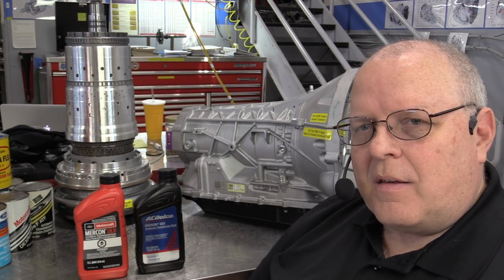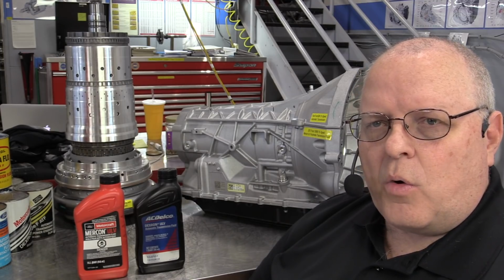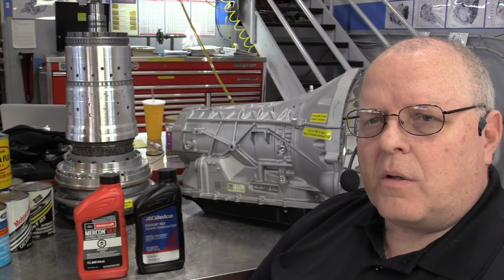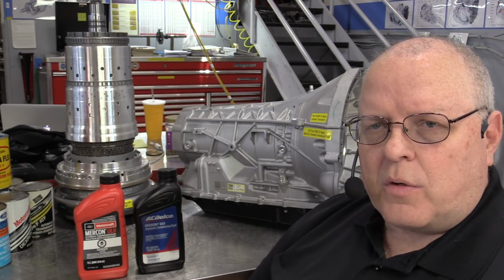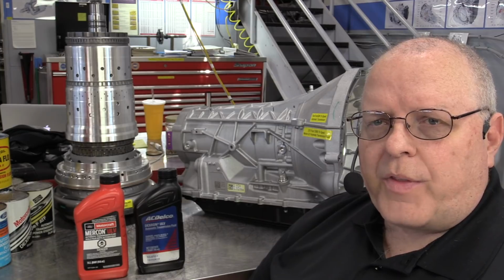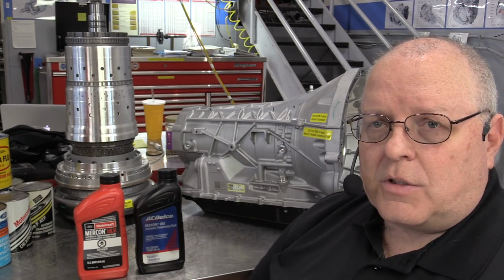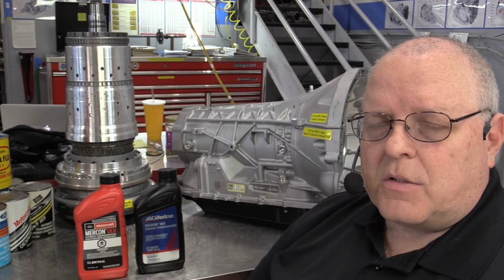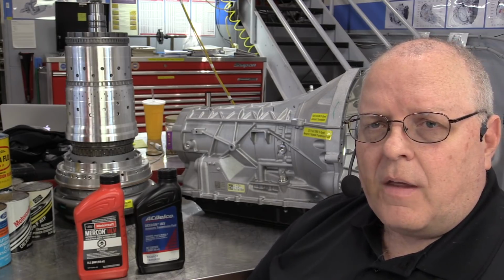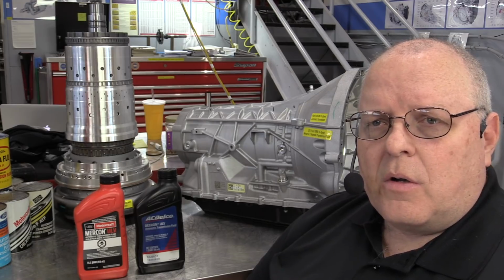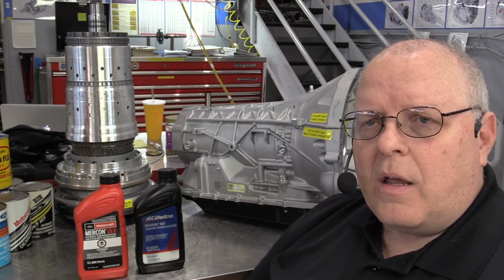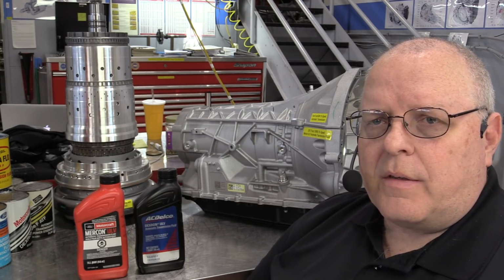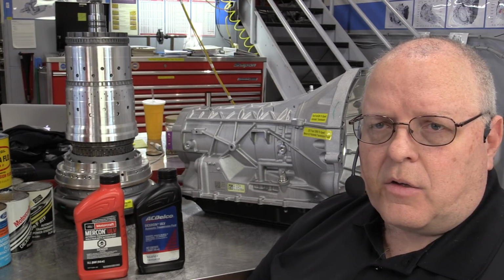If you read the maintenance guide in your owner's manual, or that came with the owner's manual on your vehicle, typically it will have two service schedules. One of them is for what they call normal driving, which, as we've discussed already, hardly anyone does, because it does not include city driving. And then it has what is considered severe service or rough duty intervals, which is typically about half of what the so-called normal service intervals are.